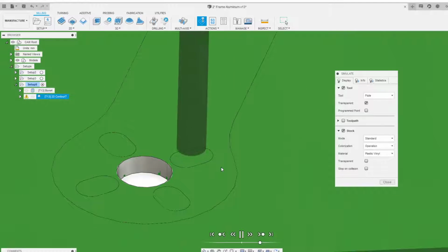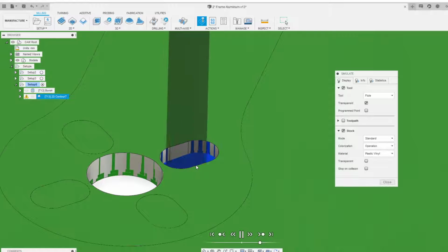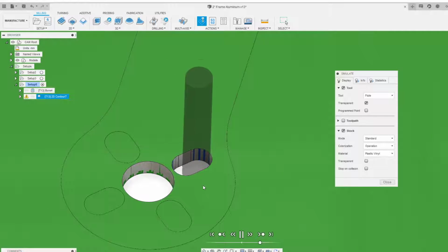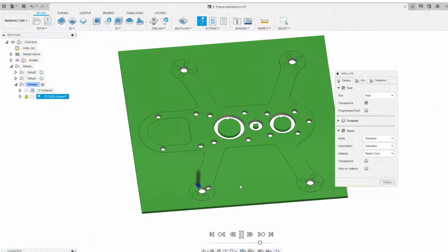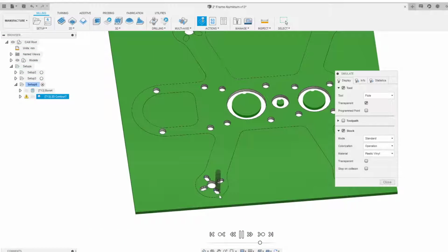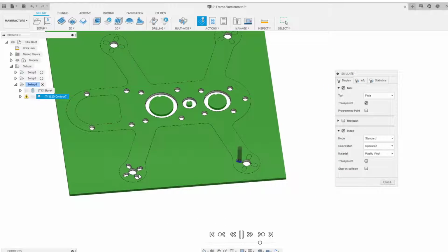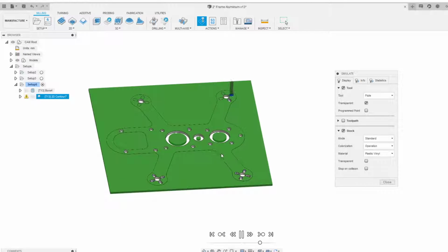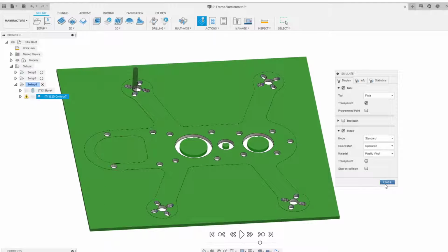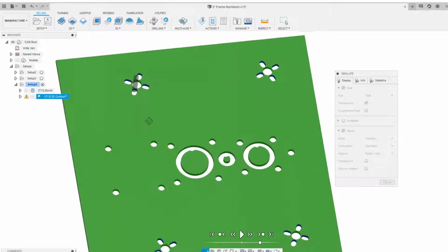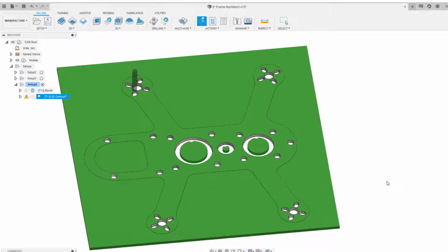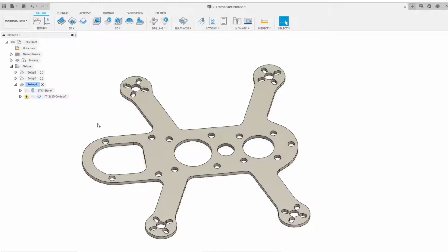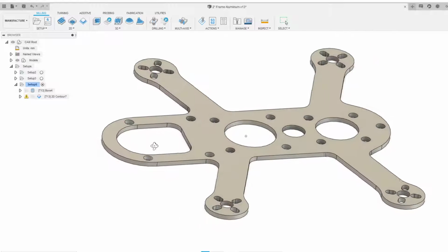So we'll watch our part, comes in, and it's just going to go back and forth around that little thing. Just zipping on through there and cutting them out. Looks good. Very tight squeeze. Those are only 2.5 millimeters, I think, and the tool is 2.38, so not a lot of buffer. All right, cool. Fast forward, turn off the model. Looks great.